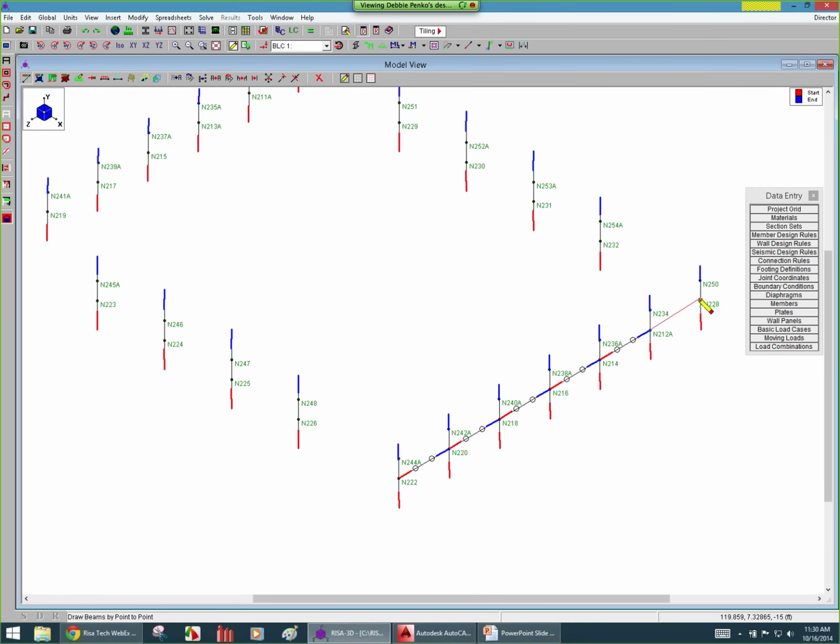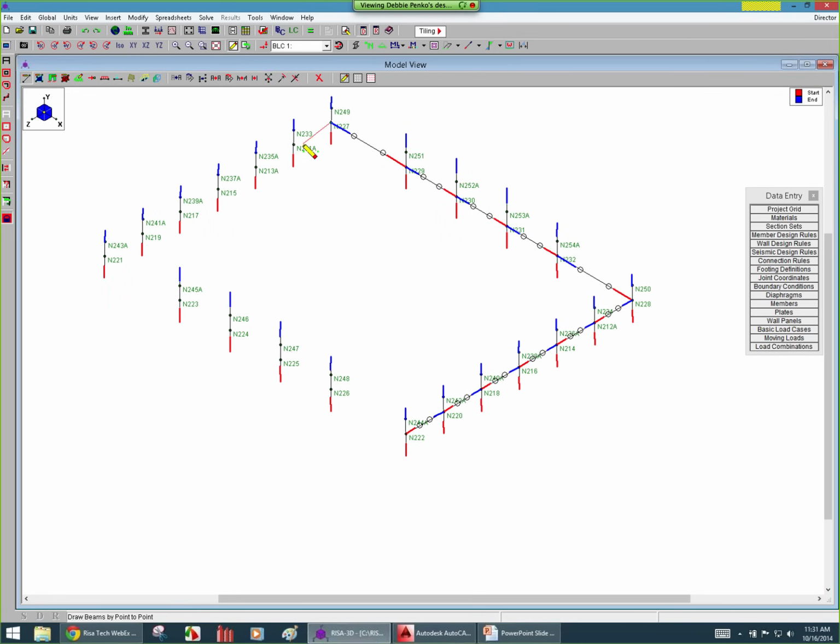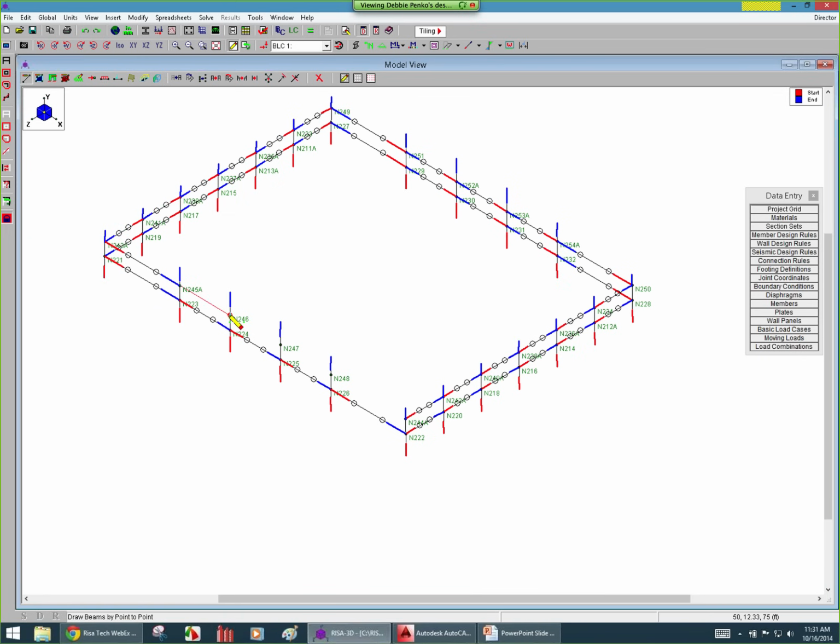Now, again, that's something you might be doing. If you are, then you might be considering it fully fixed. But the way I'm seeing anyone building these, the girt would be pinned. So you'll draw that all the way across the structure individually as segments because they are pinned. We're not going to be transferring any of the moment into those girts. They're just there to help support the sheathing and apply some of the loadings to it as well. One thing I didn't do is think about the rotation of these girts just yet. You can easily go ahead and make that modification.